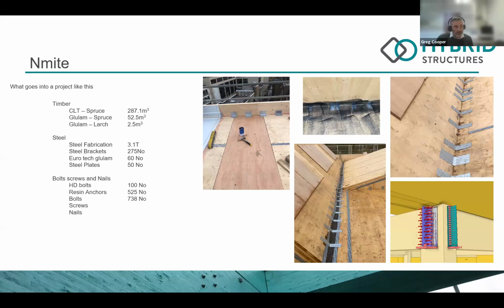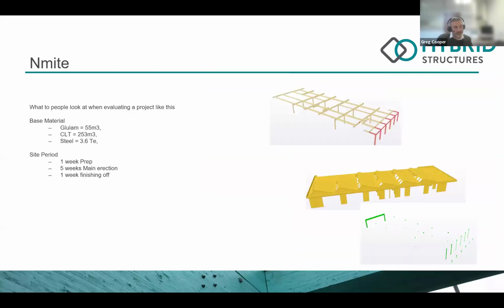But also lots of screws, lots of bolts. 42,000 nails went into this job to physically make it work structurally to stand up. That's a lot of nails, but fundamentally, they are the components that connect everything together. So in total, there's around 50,000 screws, nails, and bolts that go into this job to make it work. And then on top of that, we always have items such as DPM, packings, tapes to give air tightness, sealant, end grain sealers to protect the CLT as we go, tubes of sealant to make sure of the air tightness and packing, etc., just to physically get the building to work.